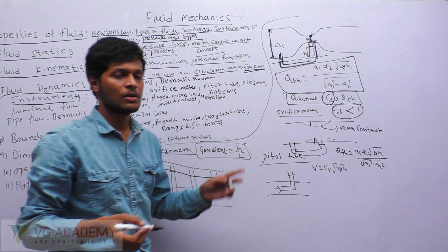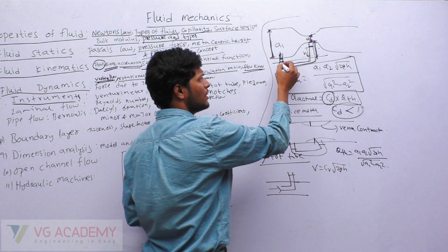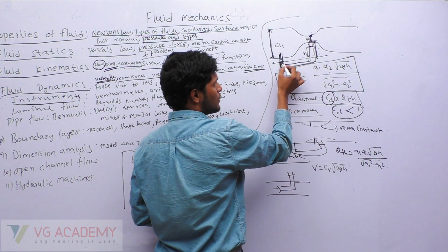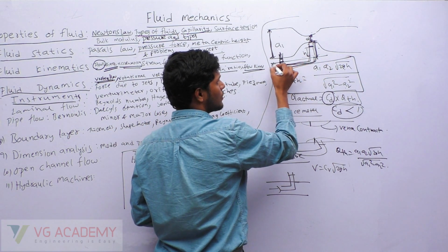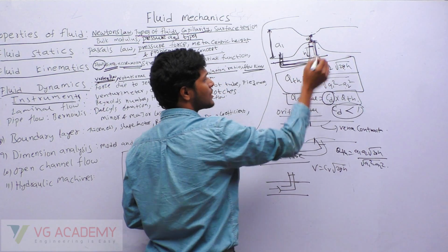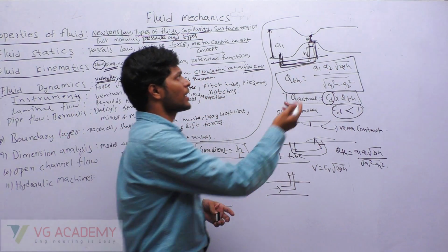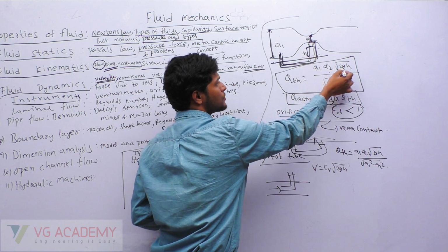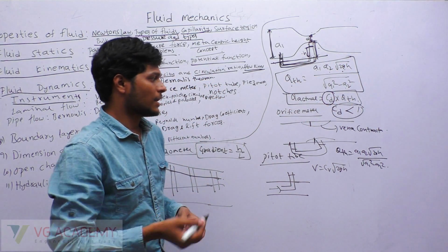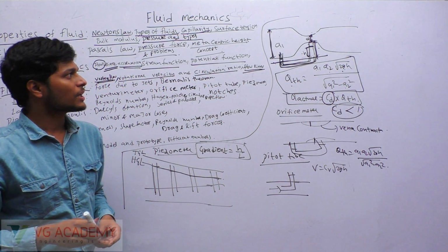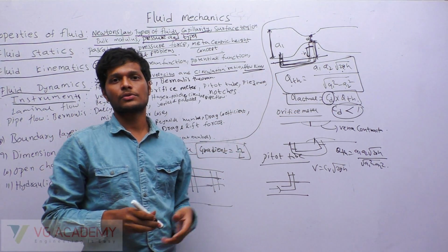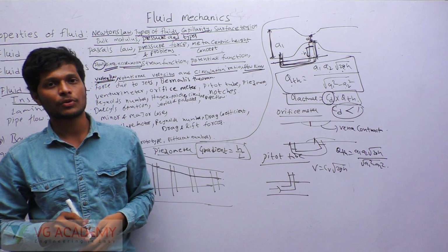This is how we have to solve the differential manometer, as I said. Whatever the liquid you have, you draw a straight line there, and you can get the pressure difference. So here you can directly get the head. After substituting, we get the theoretical and actual discharge. So that is about the venturimeter and orifice meter used to find the discharge of the fluid.